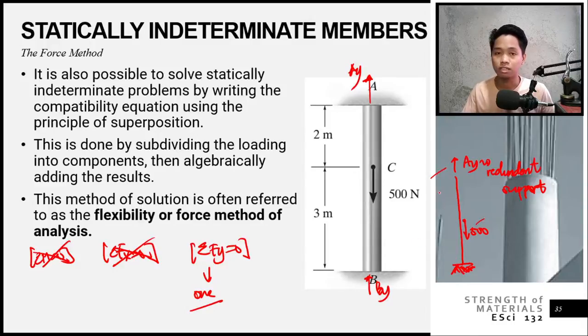This structure is statically determinate. Right? Because one reaction, right? One equation. Okay, so you get it. Alright, so by this, we can have this loading diagram. This is the loading diagram that I am showing. So that would be the new loading diagram. We have a fixed support at the bottom at B, and a free end at A. And then that is loaded with these forces.